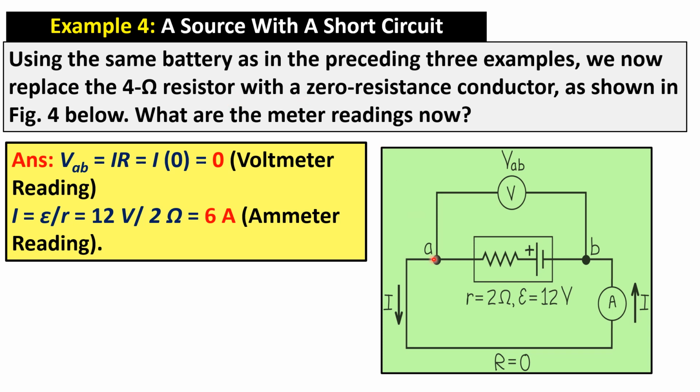Even in our household electrical circuits, short circuits do happen. One example of a source of a short circuit is using too many appliances connected in parallel. Too many gadgets and appliances connected in only one specific circuit will possibly cause overloading and short circuit as well, which are fire hazards. So just be very careful.